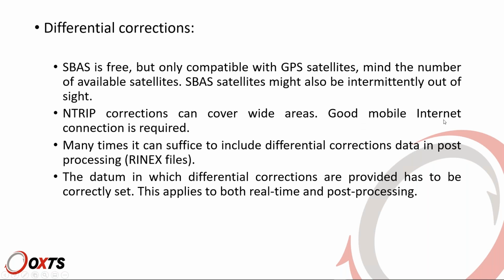What you need is a good mobile internet connection, obviously, because if you lose the connection, you will lose the NTRIP stream, and the position accuracy of your system will suffer. If you can post-process, so we are not only interested in real-time data, but you are happy to post-process, then RINEX files is definitely a good option, because you can add differential corrections in post-processing, even if you do not have any corrections in real time.